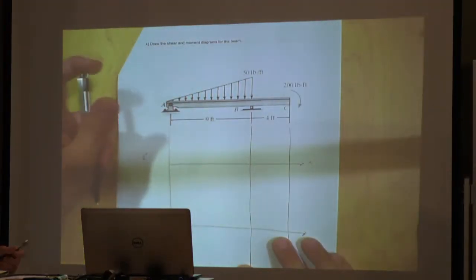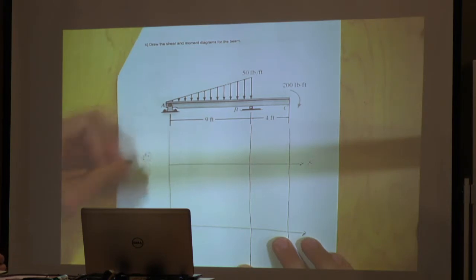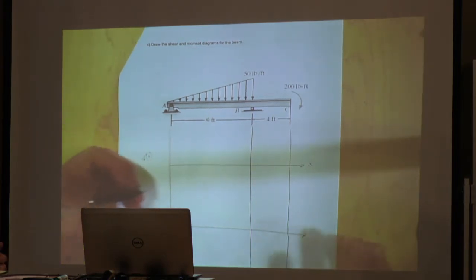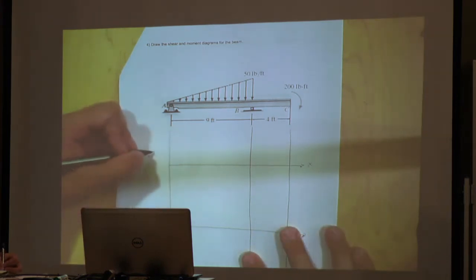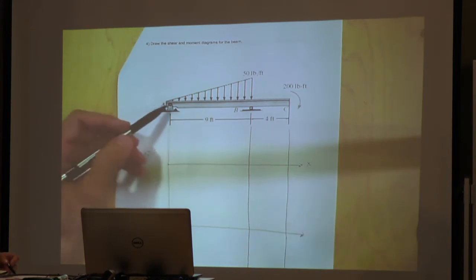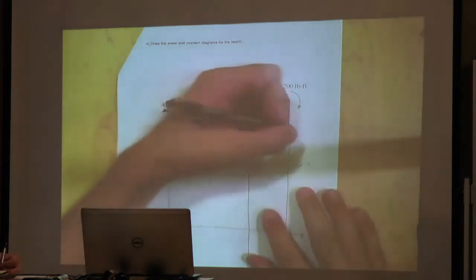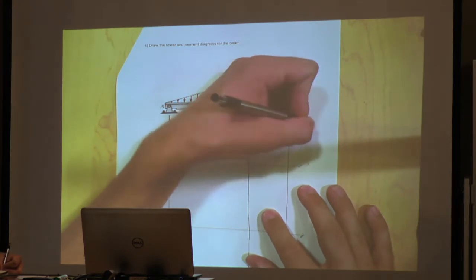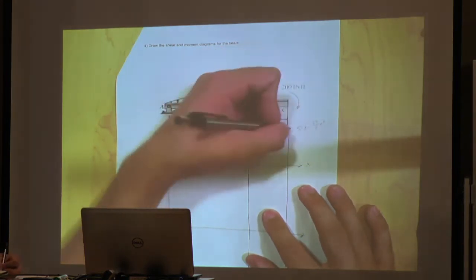And what are our units for our shear? Pounds. So shear is just a force, so you'll want to label your units. All right. So now, using the first equation, which was for our shear of 52.8 minus 25 over 9x squared.